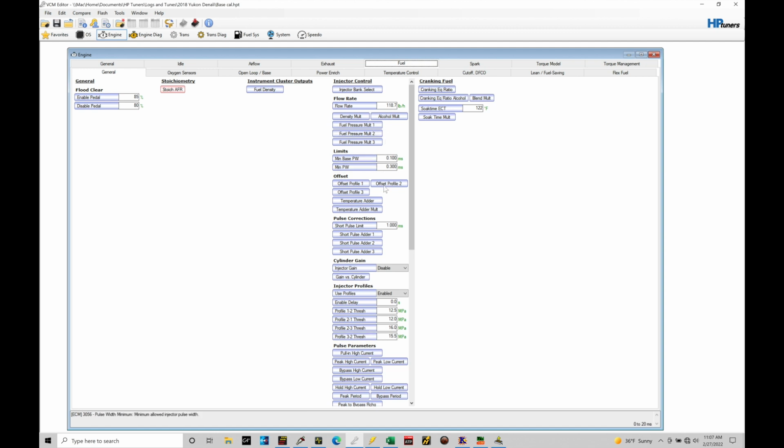All of this fits together in order to tell the engine control module how the injector flow is going to be varying based on a wide variety of conditions, such as fuel pressure or the injector tip temperature, where the injector is mounted within the combustion chamber, how hot that's getting. It takes into factor the density of the fuel that's being sprayed out of the injector. A lot of high-level modeling going on here. We definitely wanted to understand how this is all going to work.